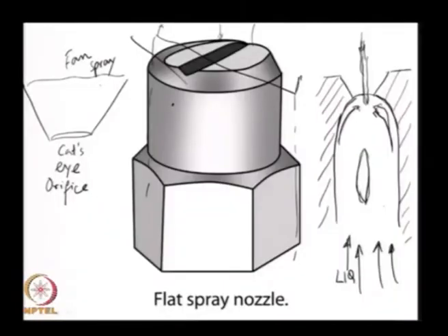In the process, if this jet were to break down and give you an atomized quality jet, so if you create drops, you are more likely to not reach the target substrate, because the same volume of liquid distributed into a collection of drops is going to have a higher drag force on it, which is going to prevent it from reaching the target. So, these next few examples are intended to show you that there are, in some instances, competing design interests that are achieved through these designs.